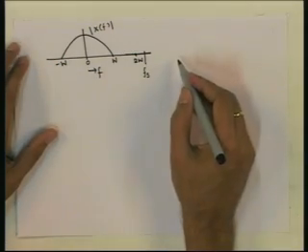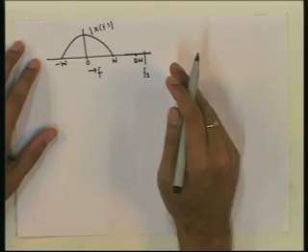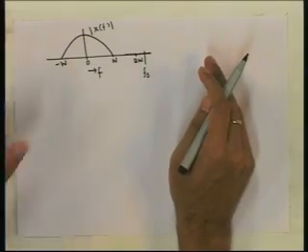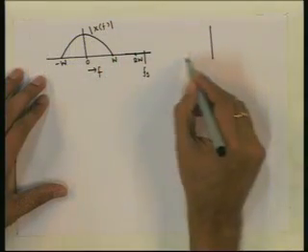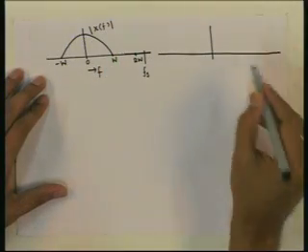Then what will be the discrete time Fourier transform of the sampled signal? We know that just like we have Fourier transform of continuous time signal, we have discrete time Fourier transform, which is abbreviated as DTFT, of a sampled signal or a discrete time signal. So, when we sample the signal x(t), we get a discrete time signal, then we can take DTFT of that signal, and how will that DTFT look like? Given that the analog signal x(t) has this spectrum, this Fourier transform, it will look like this. First of all, DTFT will be periodic with period 2 pi.